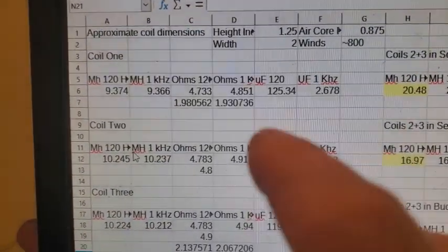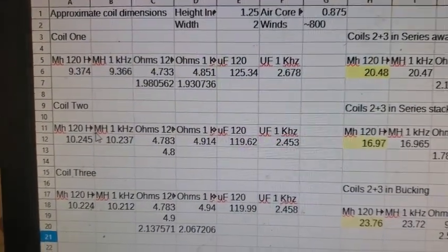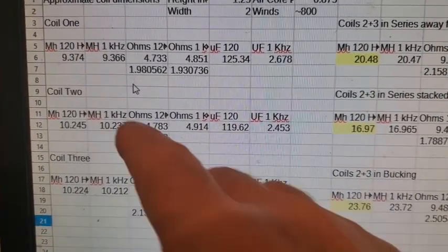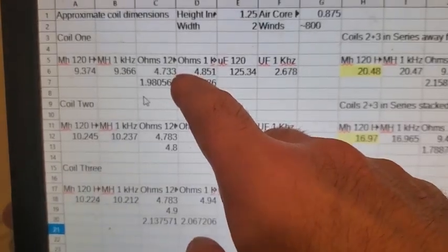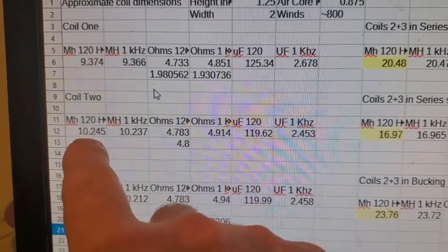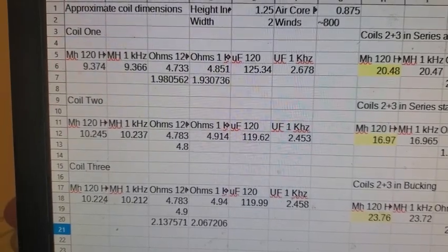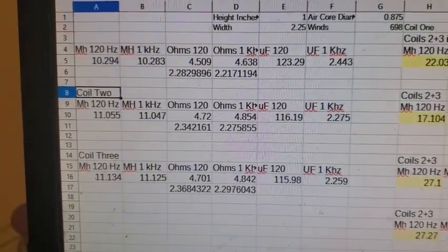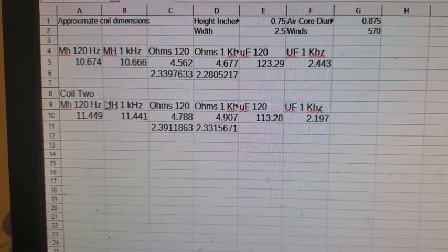And one thing that does go as I expected is that if you're just charging a coil to a set voltage, as you increase the inductance for a given length of wire with a single air core solenoid, it charges more efficiently.